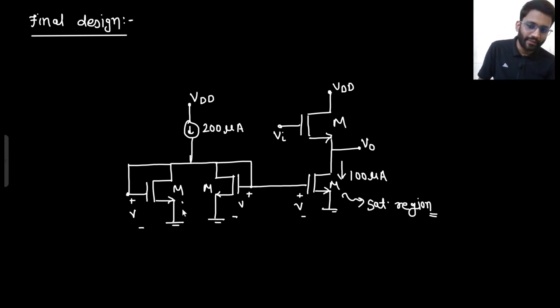What did I tell you? This will have 100 microampere current. This will also have 100 microampere current. What will they act as? They will act as a current source, and their impedance doesn't even matter. Also, let's first solve it by the conventional method. What is the conventional method? I need to look at the impedance from here. What impedance do I see from here?